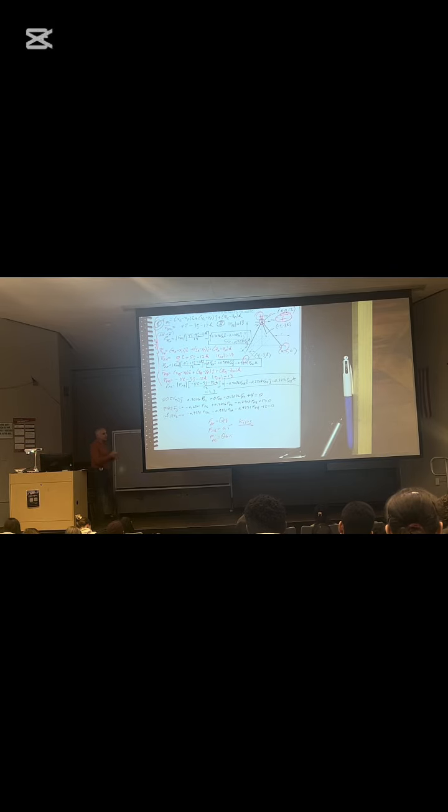Hey, doofus, you guessed wrong on tension, tension, tension. Only one of them is in tension, and that's PB. The other two are pushing up against joint B, so they are in compression. Anytime you push up against a joint, that member has got to be in compression. Anytime you pull on a joint, that member is in tension.